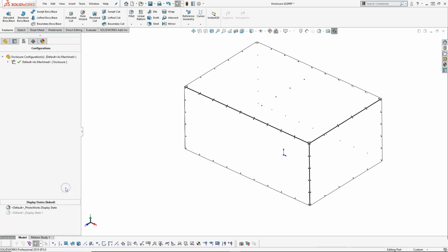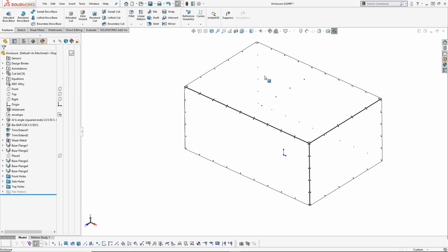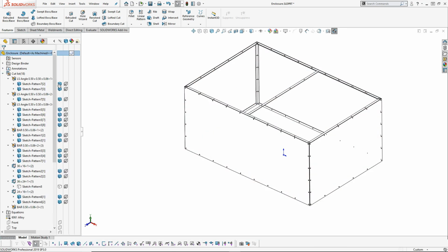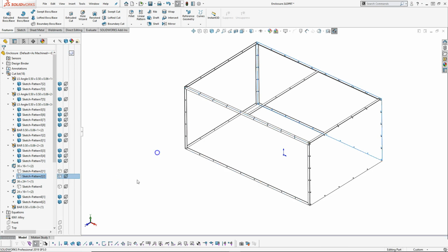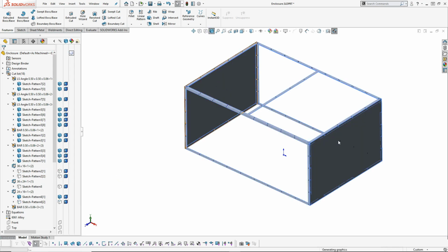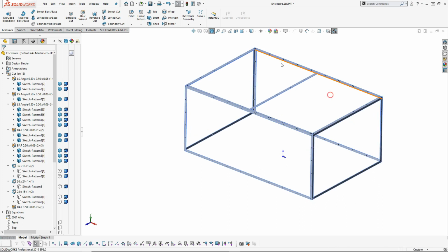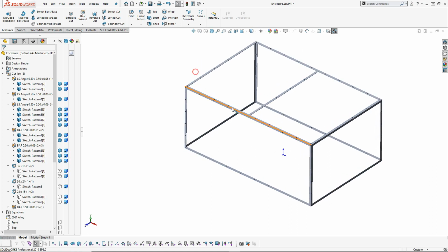So we're going to add a display state, and I'll do one with the weldment, and a single click usually allows me to rename it. Not sure again why that one's not picking up. From the assembly I can hit tab, or we can come back over here and find the sheet metal items and unclick them. I put that into the wireframe just because of the edges being highlighted. On our selections, if we go shaded with edges, shaded without, it kind of fades in.